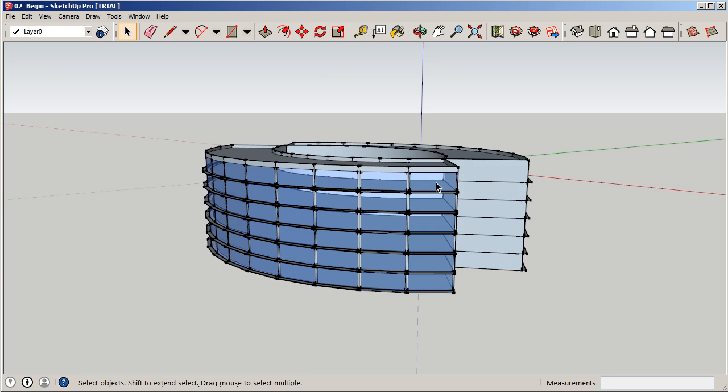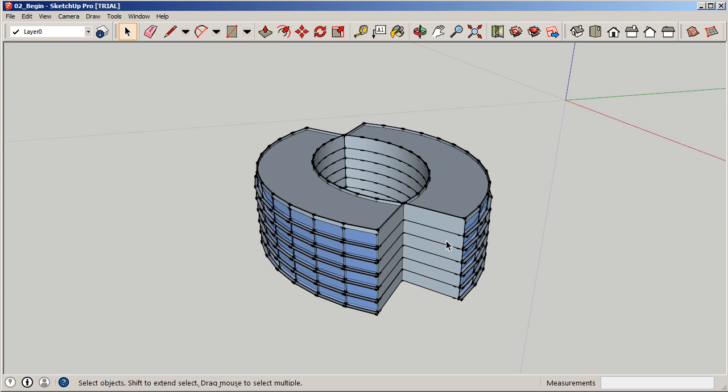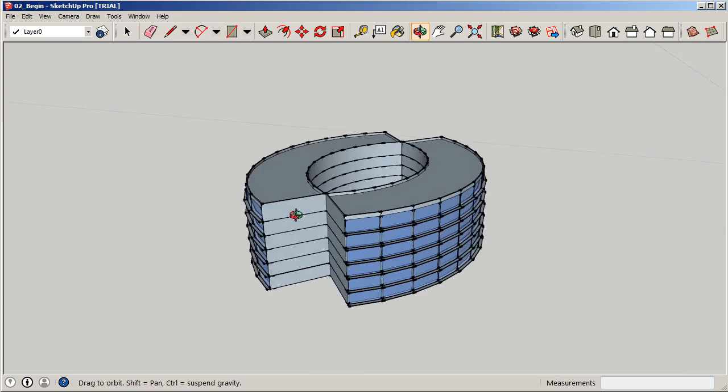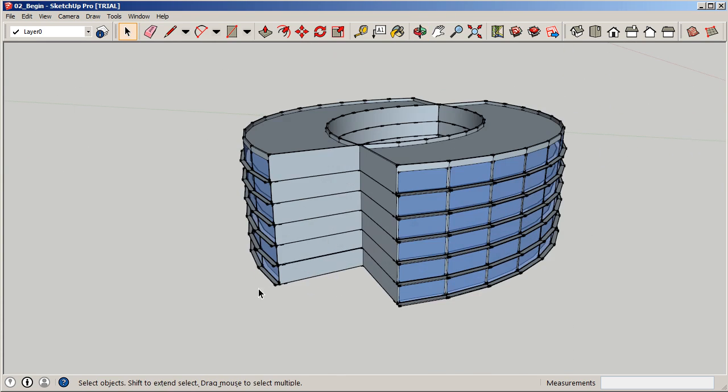So it's going to be important that our surfaces are facing the right direction so that they are visible if we're going to be using 3D modeling in Google Earth or doing some 3D printing. In our case, it's going to be for 3D modeling in Google Earth and using Google Earth as a resource. So what we need to do here is make sure our faces are all oriented in the right direction, or basically making sure we can see the white side of our faces.